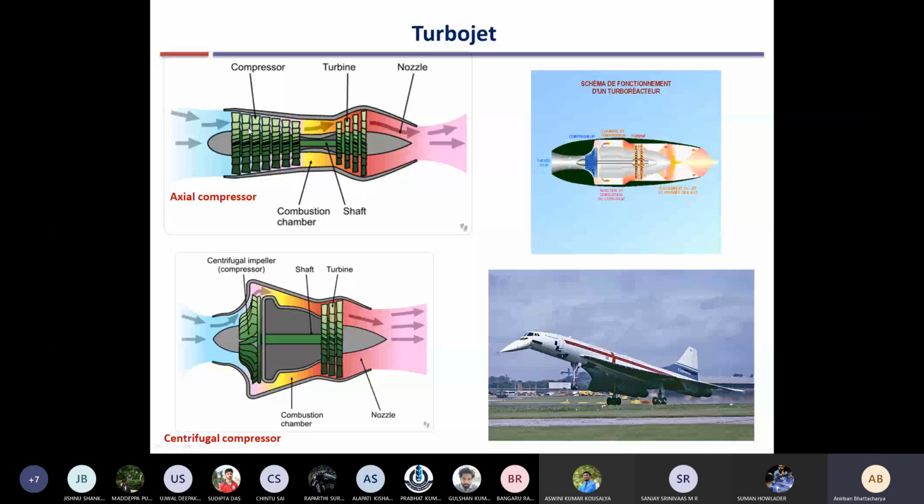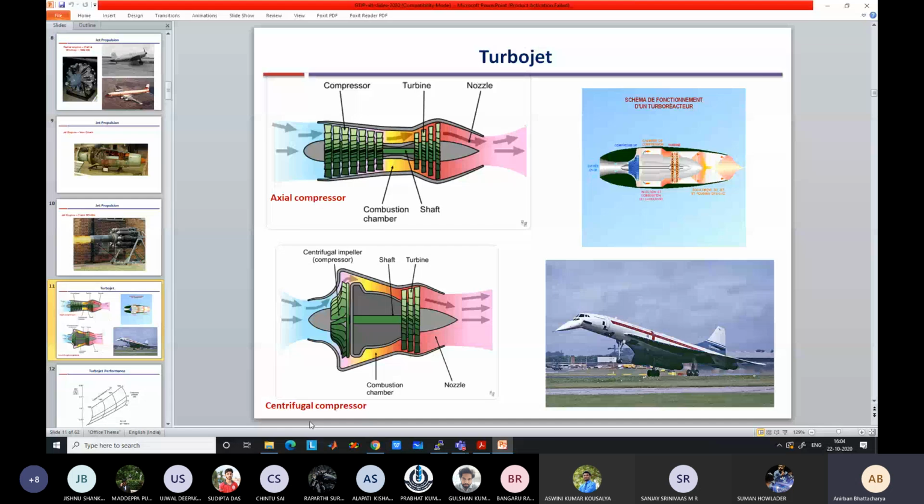And if you don't have any combustion process, the amount of turbine work output will become exactly equal to the amount of compressor work input, meaning that if you take the pressure back to atmospheric pressure, you will not have any extra energy left in the fluid to extract in the nozzle. So you need the combustion process so that the compression line is shifted from the expansion line. So for example, I will come back to this anyway.